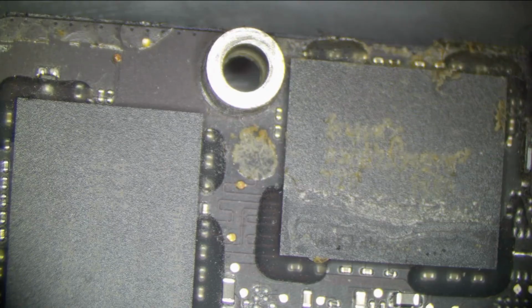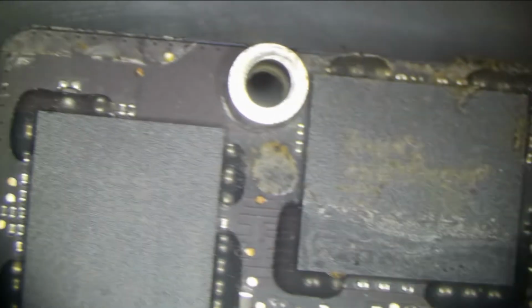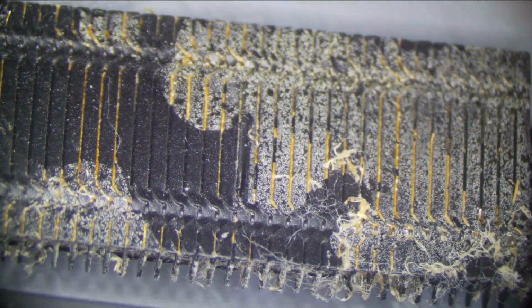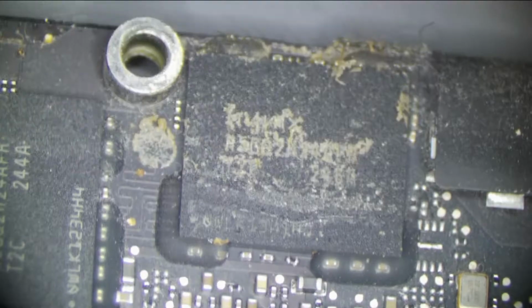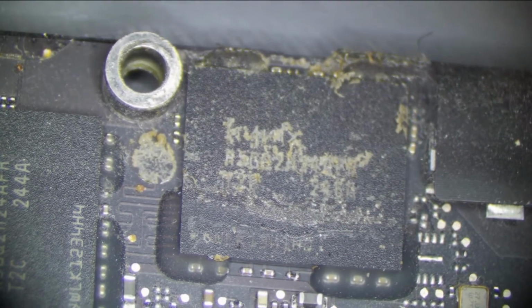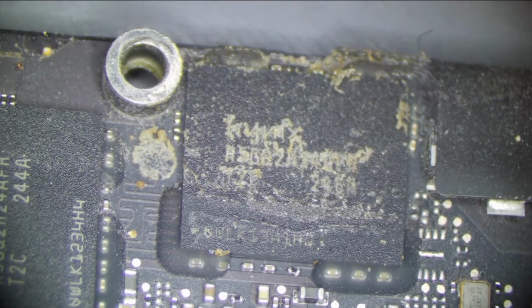Okay, our board is out of the enclosure, and we actually have a little bit of a different issue than what I was hoping for. So, you can see right here we have some moisture ingress into the computer. This looks like coffee. As you can see here, it's on the heatsink, and we also have some right by our lovely VRAM chips. So these are our video memory chips, and if our video memory chips are not working, then it's not going to work at all.